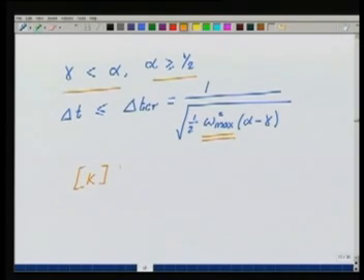k a is equal to omega squared m a. So for this system, the maximum natural frequency squared defines the time step size. Okay. So you see that the bigger the natural frequency, the smaller the time step size that you have to take. Why should you do that?